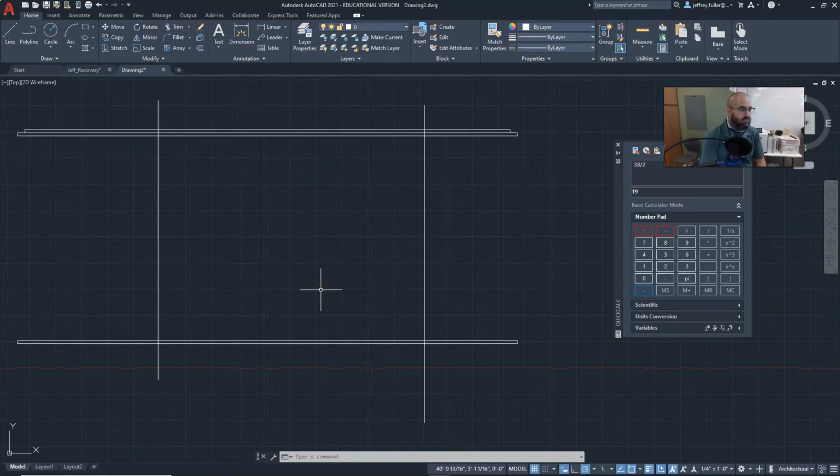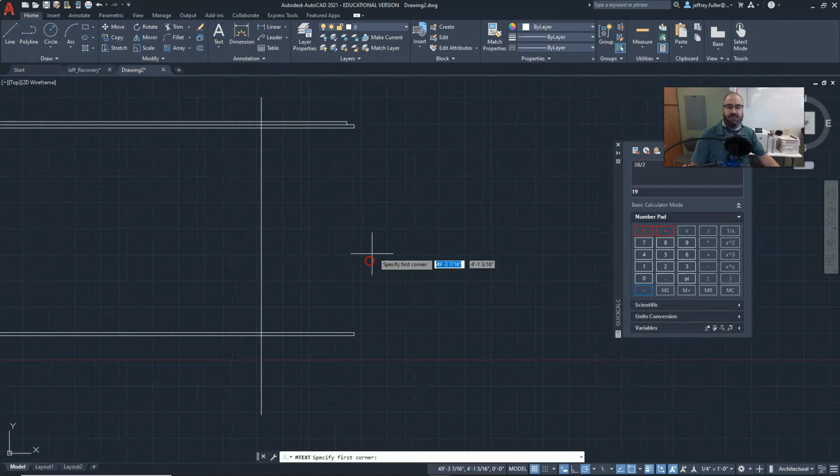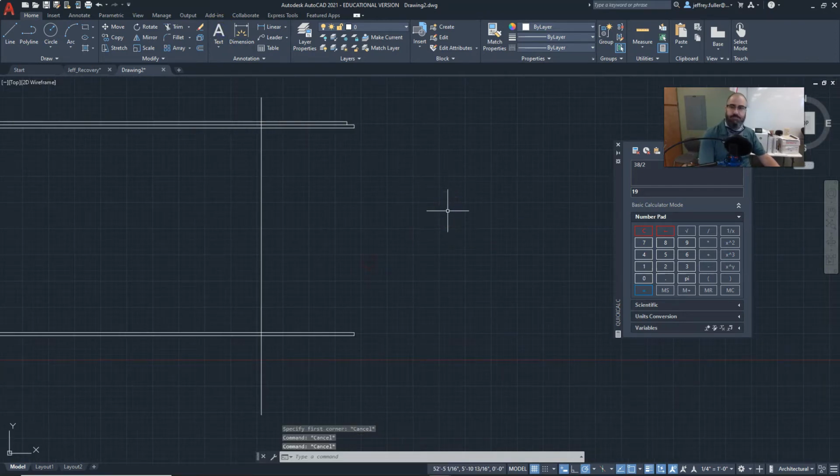Now the door in this case is going to be 36 inches wide. That's a typical width of a front door. The door we're going to get from the building supply store measures 36 inches, but it's also got a frame that comes with it. And when we pick up that door, it's going to tell us how big to make the hole, and it's called a rough size. Remember, I want you to write that down. Okay? Write that word down.